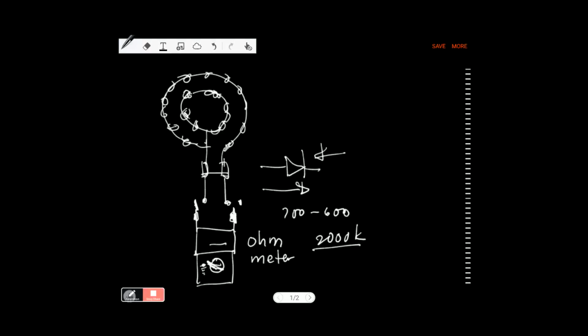However, when you put the probes on the other way around, the reading goes up so much that it can no longer be read at this range. It's beyond the capability of your meter, meaning the resistance goes up dynamically and blocks the flow.